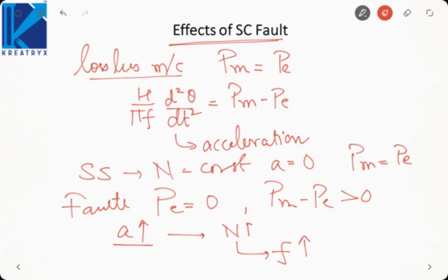But we made an assumption that the frequency remains constant under the short circuit fault condition. But here what we are seeing is the physical effect of a fault is to increase the frequency of the system due to increase in the rotor speed. That is precisely the hunting phenomenon, when the speed of the rotor changes due to sudden mechanical input on the shaft of the motor. But this is the hunting phenomenon, or these are the oscillations that we are studying in case of the synchronous generator and not the motor. More details we will study about this in the stability chapter, so no need to worry about how we arrived at this equation and how we will be using it to determine the oscillations of the machine.